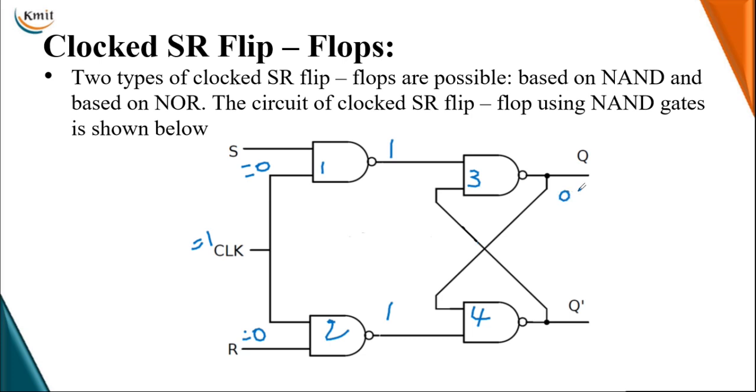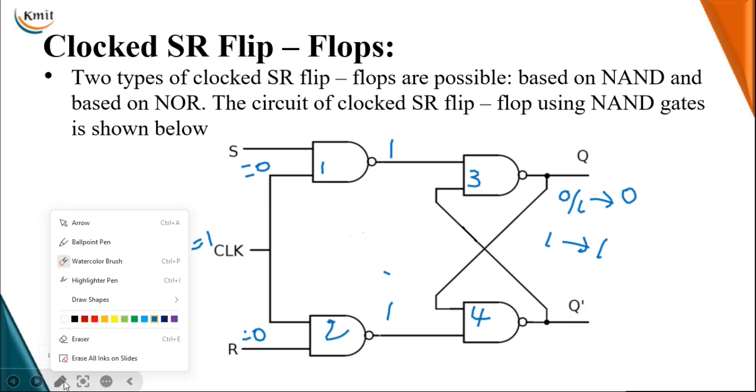So present state is 0 or 1, and the next state is a no change state. Hence if present state is 0, next state is 0. If present state is 1, next state is also equal to 1. Since my active low input SR latch inputs are 1 1, for such input of 1 1, we obtain a no change state on your SR flip-flop.